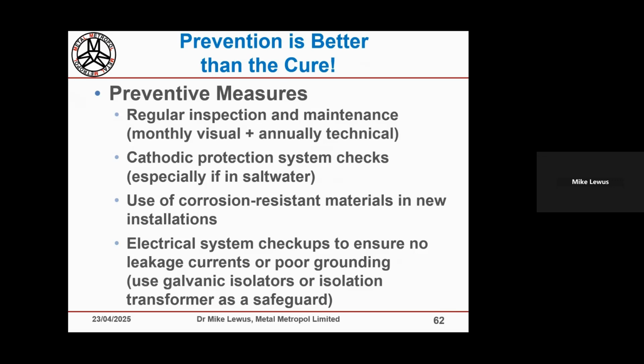I know your conventional zinc on any other sort of vessel has a voltage of about minus 1 volt. But a critical thing with anodes is the formulations. They have small alloy additions that change the voltage and the responses. Now, I just happen to know that with wooden boats, there are one or two specially manufactured zinc anodes, but they're not your conventional anodes that you'd stick on any other kind of vessel.